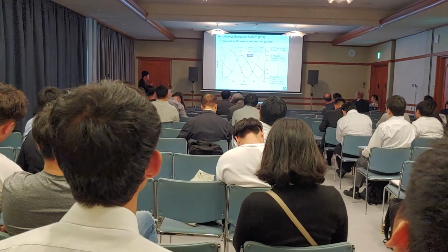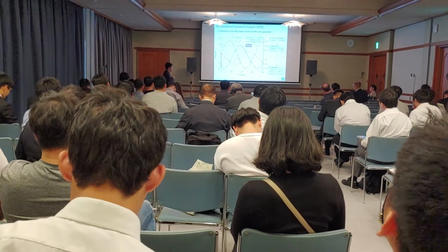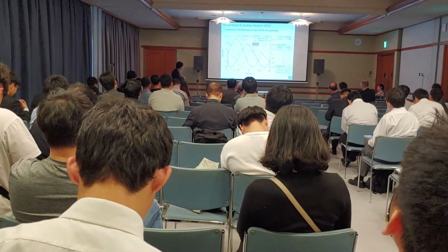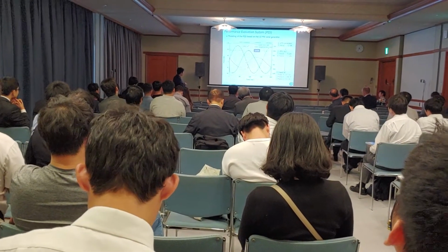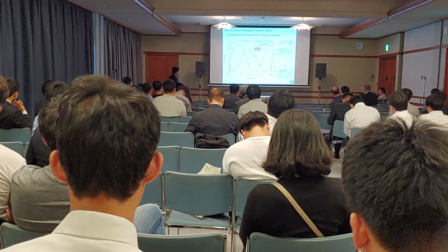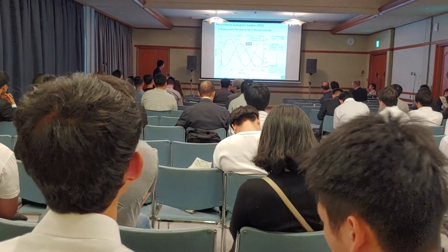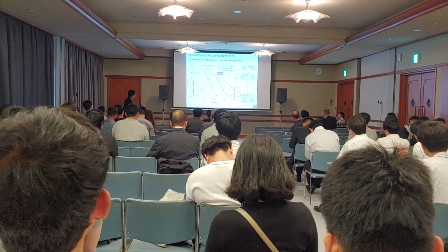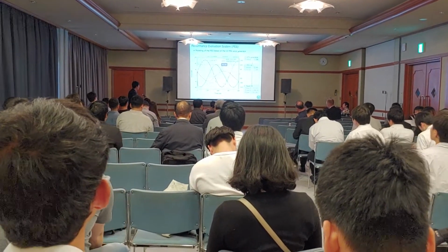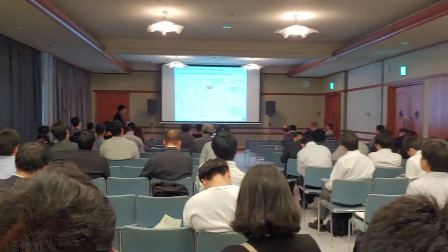Okay, it is a very important point of the graphs. You can see the maximum torque and this maximum tangential force is 72 kilonewton, and at that time the current for ABC is 790, 1,040, and also a minus current, and the direction is different, right?